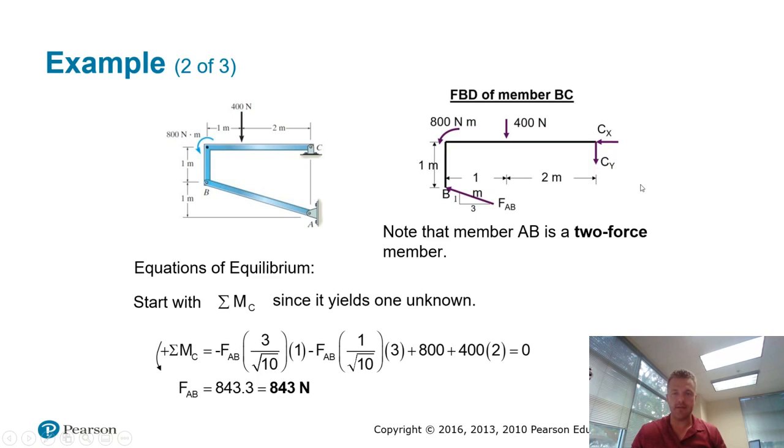So this is a statically determinate situation. Since we know this geometry would lie along the axis of member AB, I can decompose its force using the geometry that's provided. Namely, if I want to find the X component of this, first thing I need to do is create my equivalent geometrical triangle to my force triangle. I know the two side lengths of this right triangle. So by Pythagorean's theorem, hypotenuse is going to be 3 squared plus 1 squared, which is square root of 10.